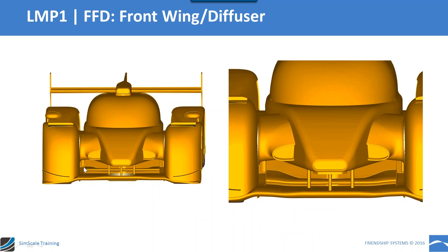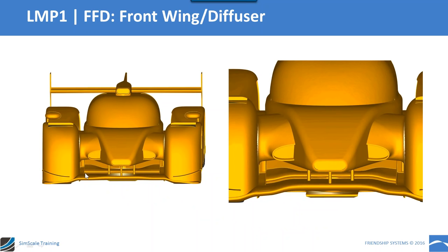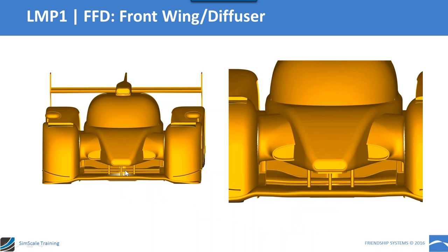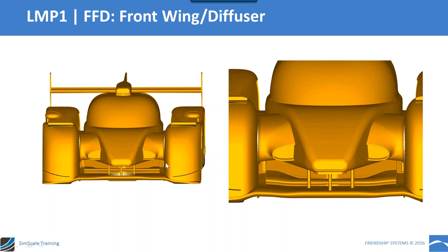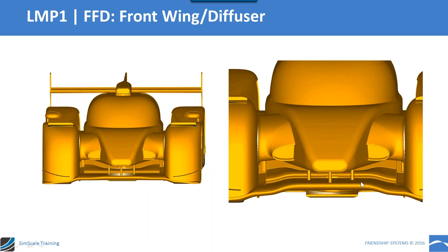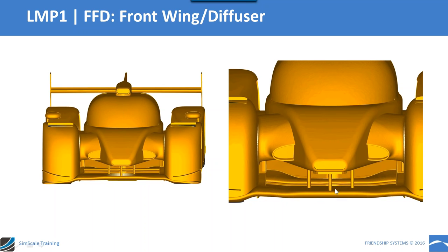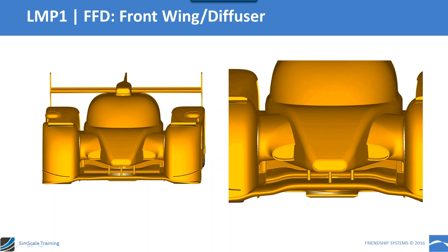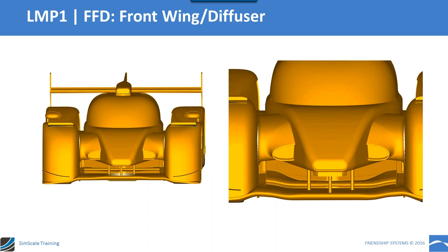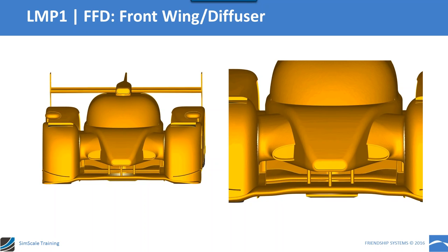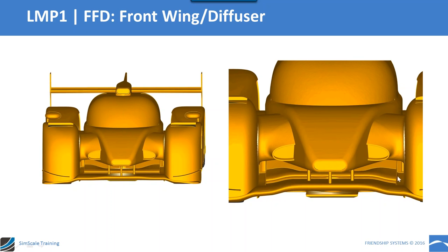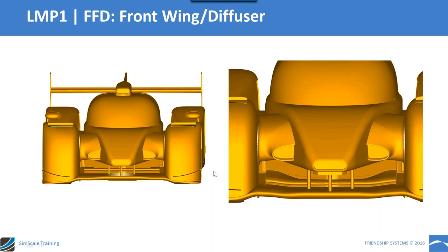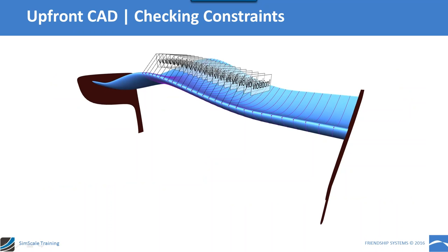You can twist your wing, or you can change the angle of attack completely, like here on the second element of the splitter, and also you can increase the height between the ground and this element. It depends on your target in the design, so you change these geometries. All right.